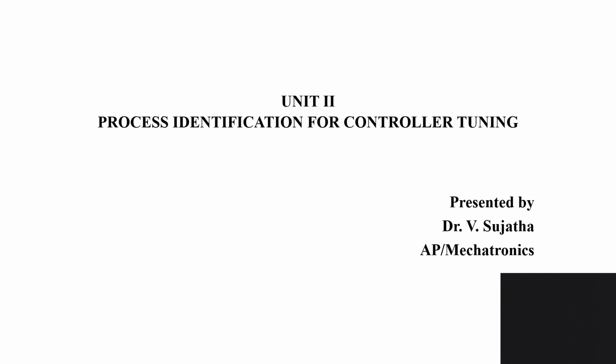Good morning, students. Today's session we are going to discuss how we are going to identify the process for controller tuning. Okay, so in the previous session we have learned about the controller tuning rules proposed by Ziegler, Nichols, and Cohen-Coon. So once a controller tuning rule is proposed, next you have to identify. Okay, so before designing the controller, first you have to do the process identification.